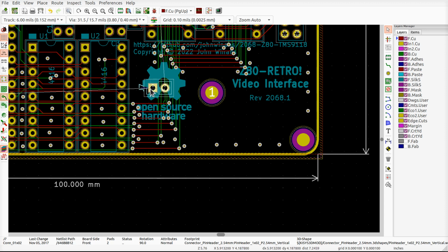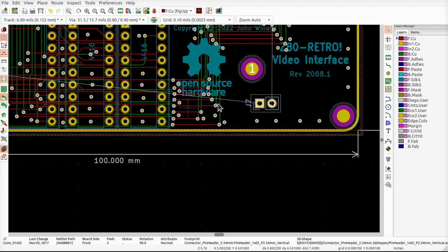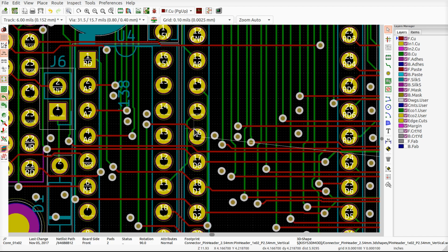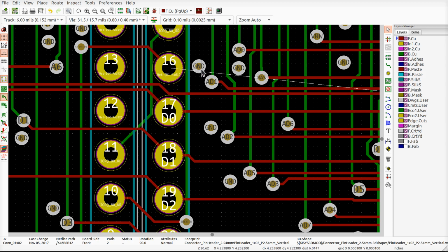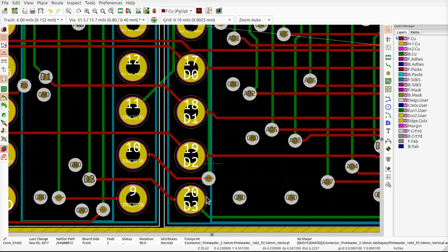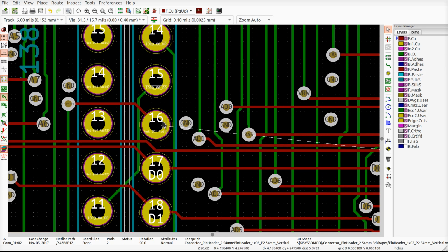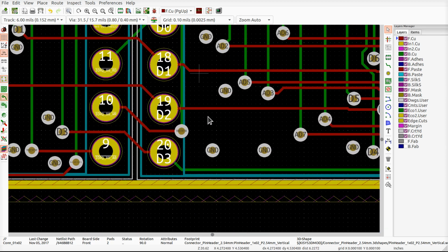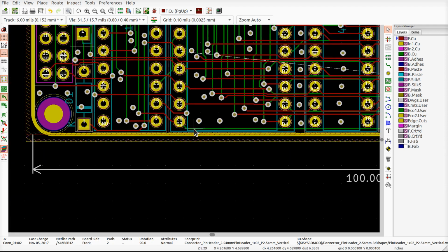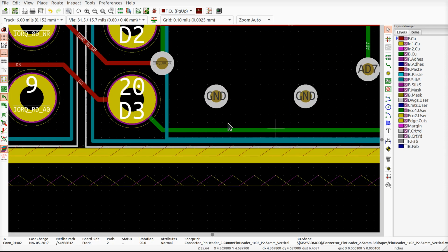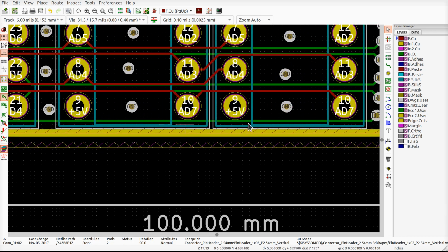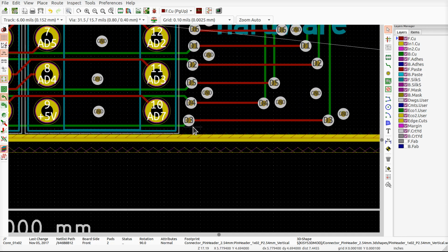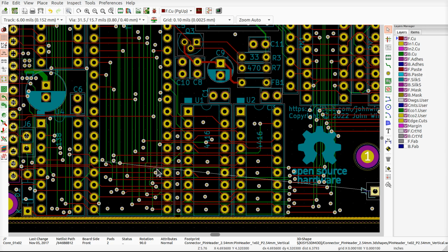No, it's 60 hertz, right? But compared to a data line running at 10 megahertz, it's relatively quiet. So from here, I can sneak a track out on the... Oh, there's a green one blocking it there. Well, I can bring out a track on the top over to here and then come down like that. Then on the top layer, because the bottom's already got this other one going across here on D3, I can run it right on top of D3 here, but that would really not be pleasant if there's any noise induced through the board, which could happen because this is a 2-layer design, I believe.